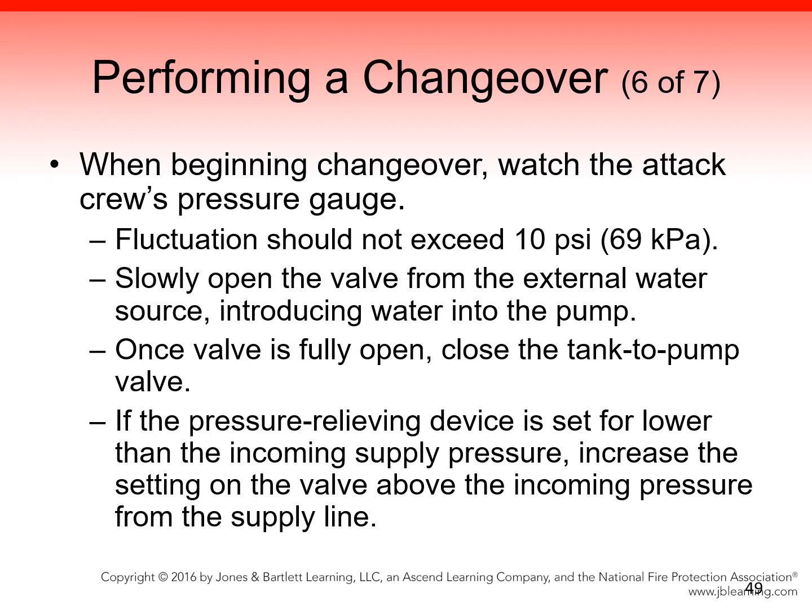The tank to pump valve does not need to be closed on the newer apparatus. A check valve will close so as to not allow water to flow into the pump from the tank once the supply line intake is opened. Many departments leave the tank to pump valve open as an extra safety feature so that the tank water will automatically flow into the pump if the pressurized supply is lost and the driver-operator is remote from the pump